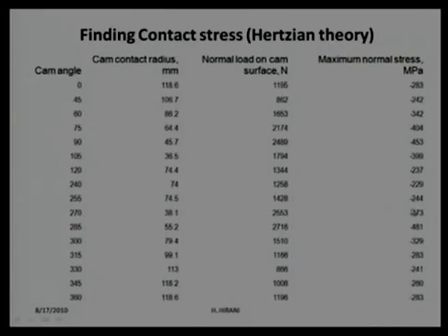We can find the maximum compressive stresses estimated using Hertz theory. The stresses first decrease, then increase, reach a maximum value, and again reduce. Since the load was higher, the stresses are higher, roughly 473 megapascal.